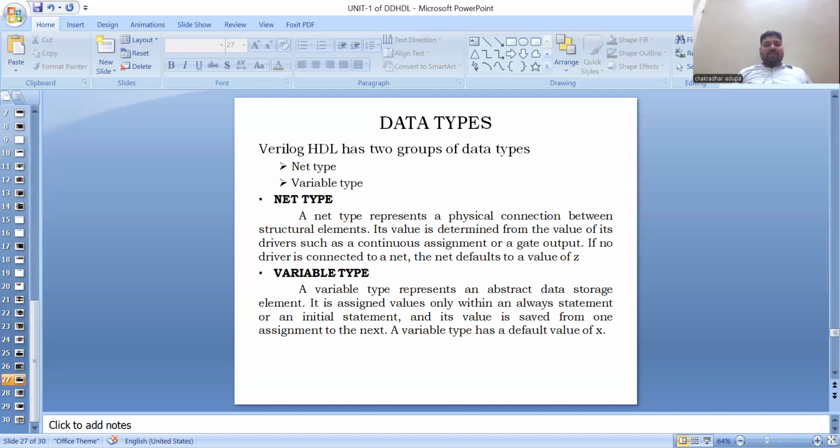And another one, if you observe, wire [31:0]. Here it indicates bus A, comma, bus B, comma, bus C, combined in a single declaration. All three buses A, B, C are 32 bits wide, with MSB as 31 to 0. It indicates that bus A is capable of carrying 32 bits of information, and bus C also carries 32 bits of information. So this way, we can declare the buses in a combined fashion with wire [31:0] bus A, bus B, bus C at a time. Individually also we can declare, and combined also we can declare like this.